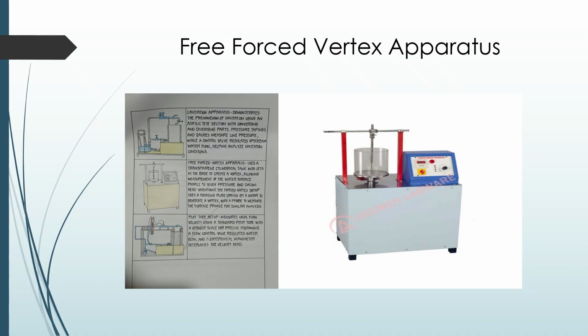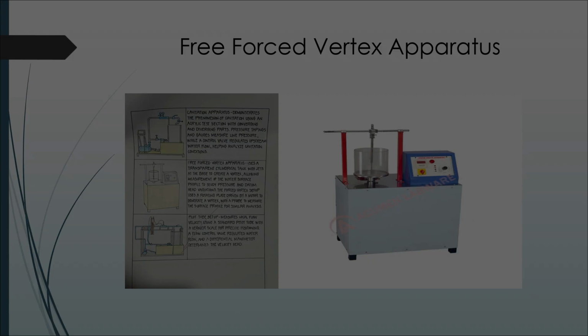An upper probe is placed in a transverse direction, horizontally and vertically across the full diameter of the vessel, so that the water surface profile can be measured. Both axes contain graduations so that the exact position of the probe can be recorded. This experimental procedure involves measurement of the resulting free surface that is calculated by the variation of the sum of the pressure head and datum head. A drain pipe is provided to drain the vessel when not in use.